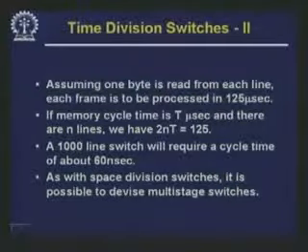So, this is the basic time for frame. Okay. And in the entire time division hierarchy, as we will see, time division multiplexing, this 125 microsecond is a very sacred figure. Everybody sticks to this figure, so that a voice call can smoothly fit into this. Of course, if you want to have a higher speed channel, then in the same 125 microsecond slot, you may pack in a large number of bits, that is all right, but we keep the frame size to be 125 microseconds.